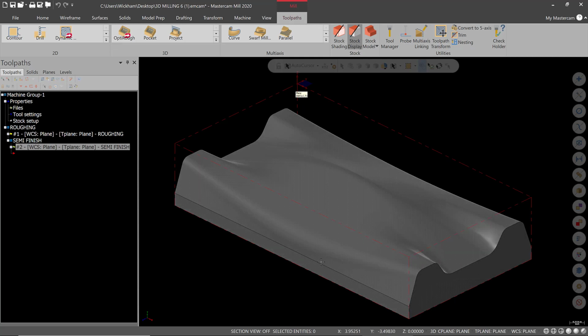The other thing you want to do is make sure that if you have a bunch of these to do, that the width right here is identical for each workpiece. Otherwise, you're going to have weird things occurring here where it's not machining. Again, the way to avoid that would be to machine the entire setup right around, but sometimes that's not necessary. It's more time. It may not even matter. So just make sure you take that into account and don't stress about this little red here, because again, technically that material is already gone. All right, so let's do a new toolpath group.